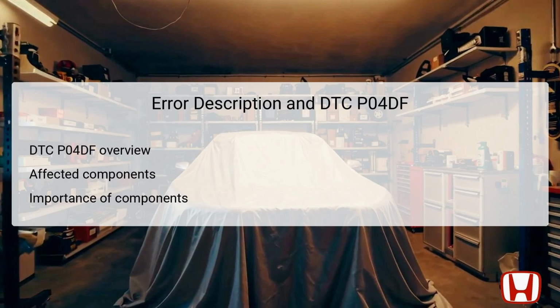The evaporative leak check module monitors the system's integrity, ensuring no leaks are present. When the pressure detected by the ELCM is greater than what the baro sensor reflects, the PCM will interpret this as a fault, triggering the DTC and necessitating diagnostic action.